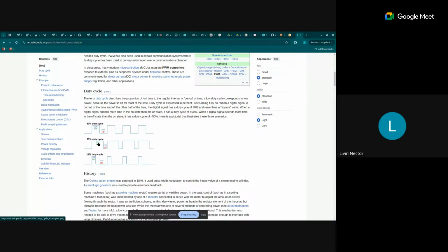And 50% of the voltage, and 70% power. I think it's about the power. I'm not sure about the physics and electronic theory behind that. But the idea is this: it simulates the voltage by turning this GPIO pin on and off at different intervals. The more time it is turned on, the higher the voltage is. The less time it is turned on, the lower the voltage is.